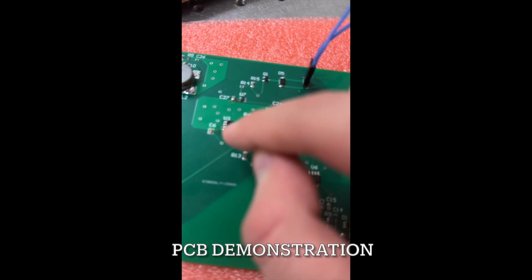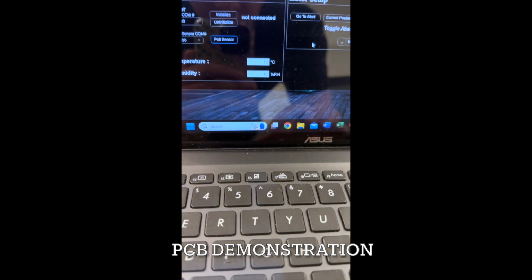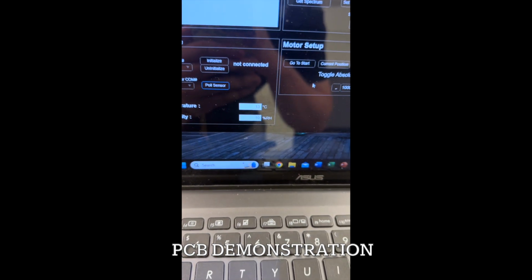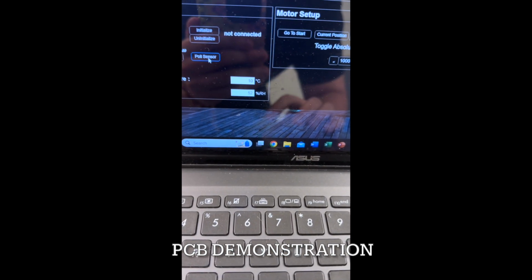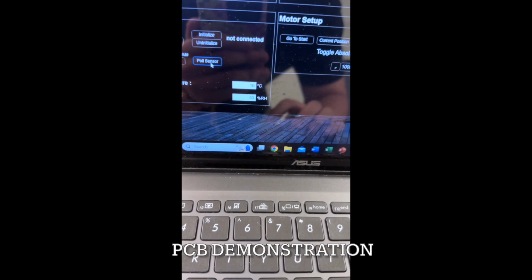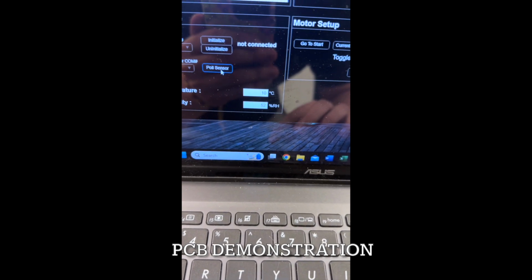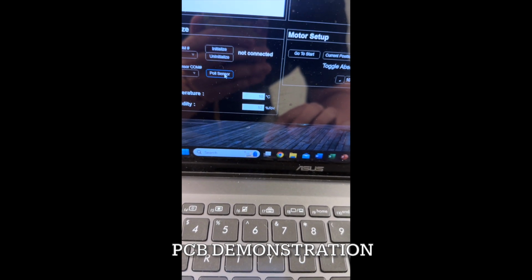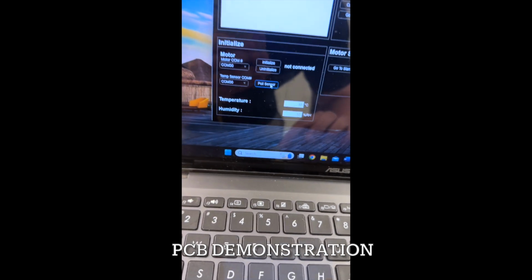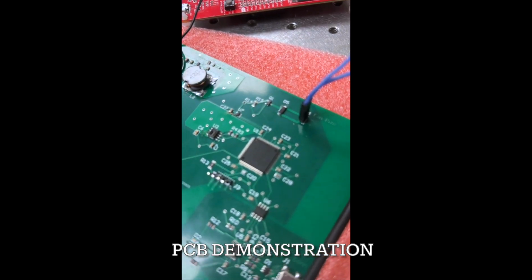Here we have this humidity and temperature sensor. This humidity and temperature sensor connects through UART, through this USB cable, to the PC here. We see that we have 13 Celsius and 10% RH. Every time that we poll the sensor, we get new values. Sometimes we're getting a surge of current, which gives us very high values at times, but they go right back down. And the reason we see such a low value for the Celsius right now is because we have the fan running onto the sensor.